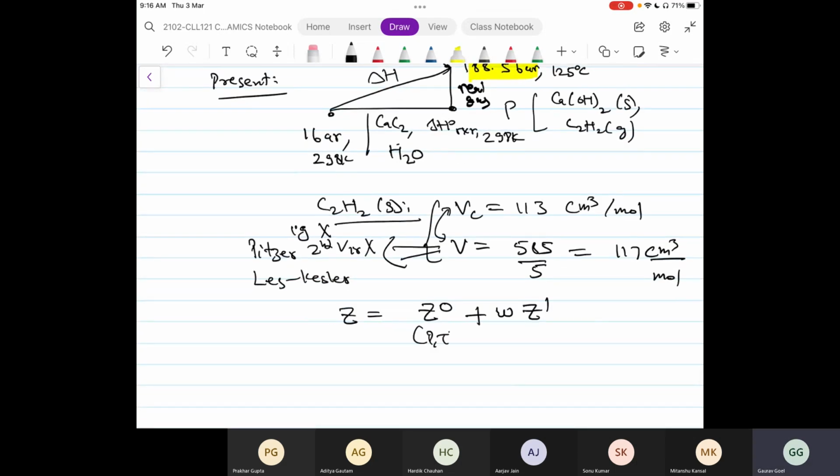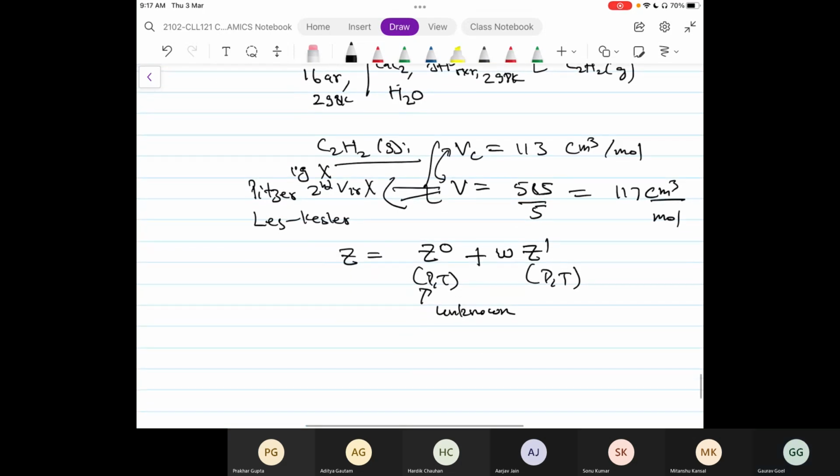So these are functions of pressure and temperature. So you can see the problem in some sense that your P is unknown. All right. So this is in a way becoming an implicit equation. So the way you will solve it is, you will make a guess for pressure. So what will be your initial guess for pressure? Temperature is known, specific volume is known. Take the initial guess as equal to the ideal gas value.